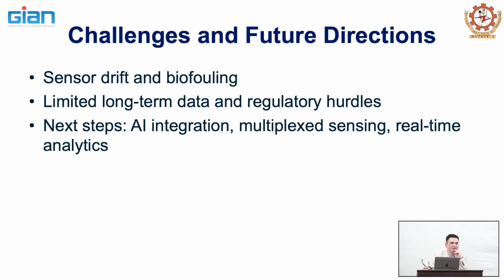I did mention that when we were doing the studies in humans, the sensor was designed so that we would have a glucose sensor and a lactate sensor. However, the bioinstrumentation that was available, although it claimed to be a multi-channel potentiostat with a multiplexer, wouldn't allow us to measure more than one channel. So we had to attach two devices with two potentiostats. So imagine both the hands with two devices measuring glucose and lactate, and then asking this person to then run on a treadmill and cycle and do things like that, right?